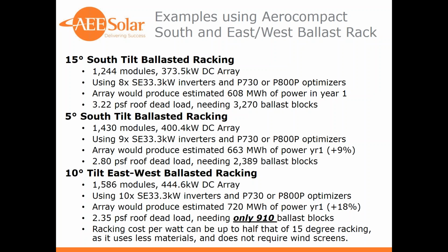Definitely would like to consider either the 5-degree south racking or the 10-degree east-west for some of your commercial projects that really need to be competitive, be at a lower cost, and to produce more power overall for your customers.